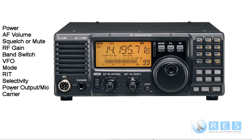Power output or microphone gain. The power output on single sideband is controlled by the microphone gain. So if you had a power meter attached to this radio, an SWR meter, when you're transmitting, you can adjust your power output by adjusting the microphone gain. The microphone gain is very important because it controls your power output on single sideband.